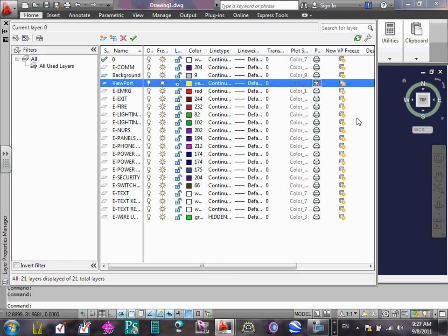Viewports, guys, are for you to scale the drawing, but not to print, because it shows another line that aggravates people. Okay, cool? So, everybody has seen all the layers, and we know how to add a layer by clicking here. We added two, background and viewport, gave them a color, and made the background gray, because you want to be able to see things.